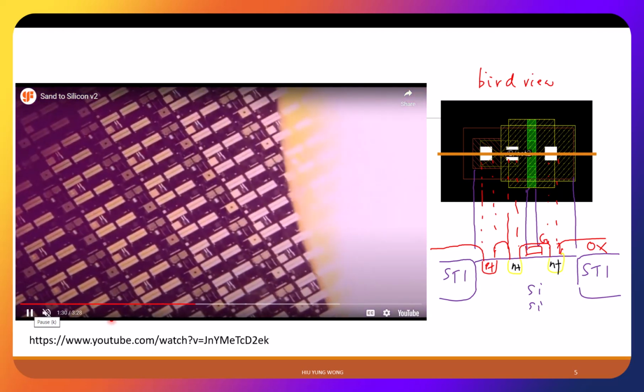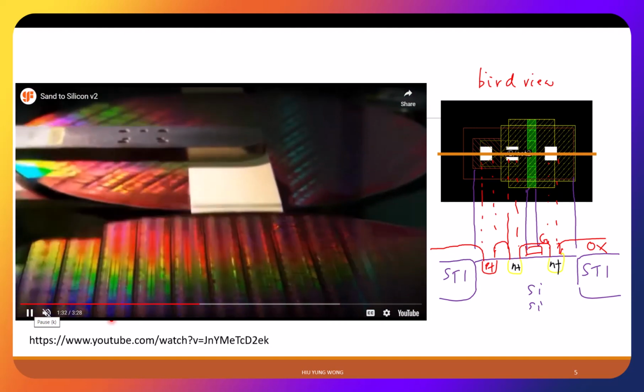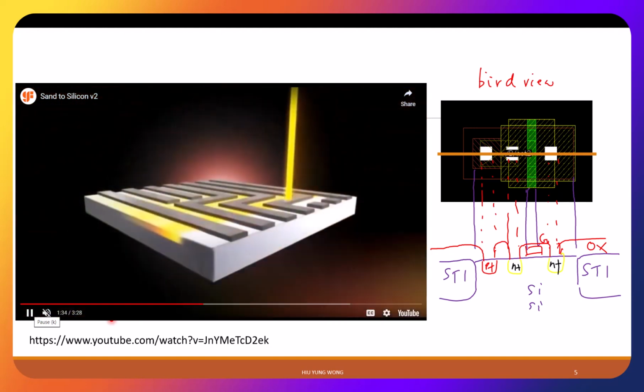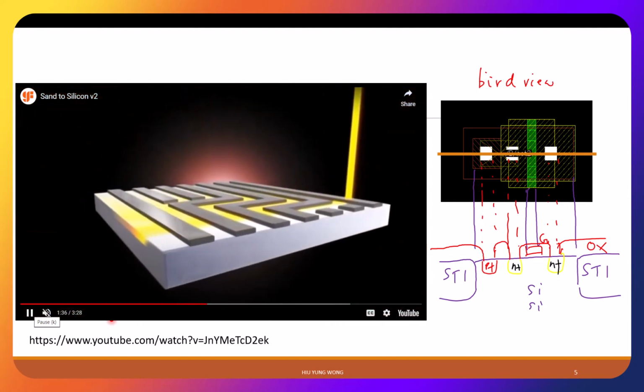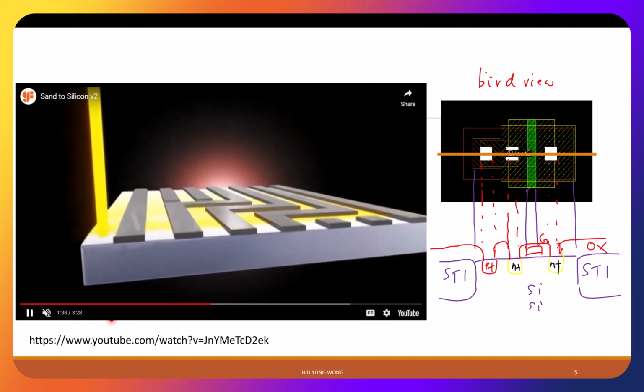Okay, then this is a finished product, right? Now they handle the wafer. Now this is what I believe is the annealing. In the past, when you implant the atom, you damage the crystal somehow. The phosphorus atoms don't sit in the right location, so they are not activated. You don't get the electron and hole you want.